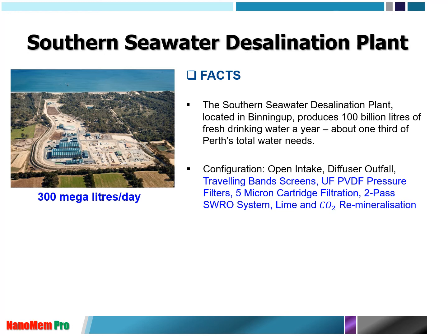One is ultrafiltration, the other one is dual media filtration. Also, a little bit of difference in post-treatment. Some places just utilize CO2 remineralization, some places lime and CO2 remineralization, and some other places incorporate lime, fluoride, and CO2 remineralization.